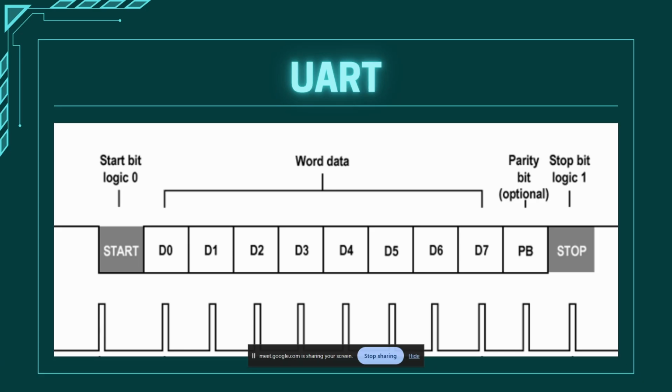Or sorry, it will perfectly read every bit once. As you can see, if I'm reading here, and then I'll wait for some time, and because I know the frequency, I'll exactly read at another point. So there might be a skew, like I might be reading just the beginning of this bit, or just the end of this bit, or some arbitrary intermediate value, but I'm reading each and every bit perfectly because I know at what frequency I'm transmitting the data. So that is what UART is.